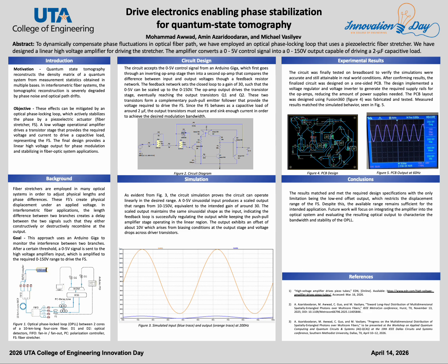As shown in figure 3, the simulated input and output traces are shown. It's done to verify that the design is achievable and will give us the results that we require. As shown, there's a 10 volt offset, which is due to the biasing done for the transistors.